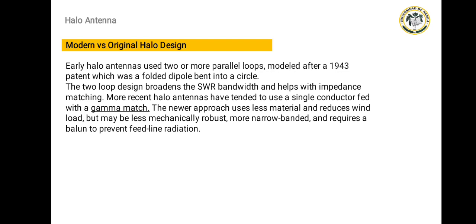The newer approach uses less material and reduces wind load, but may be less mechanically robust, more narrow-banded, and requires a balun to prevent feed line radiation.